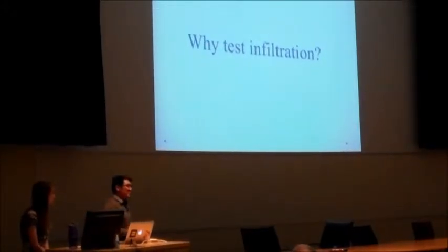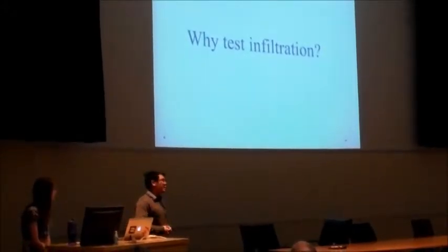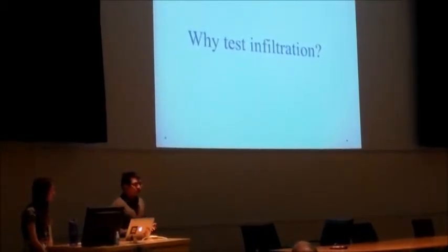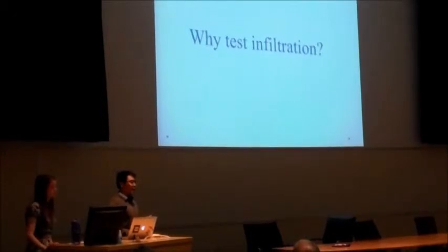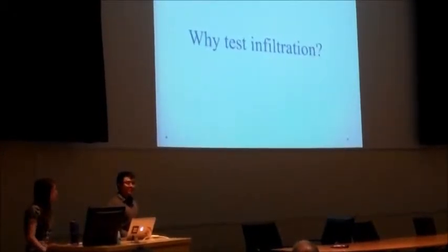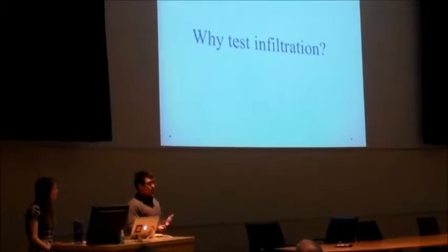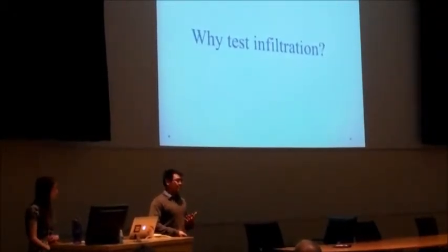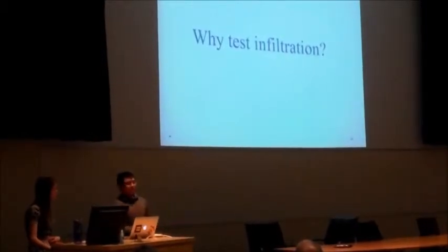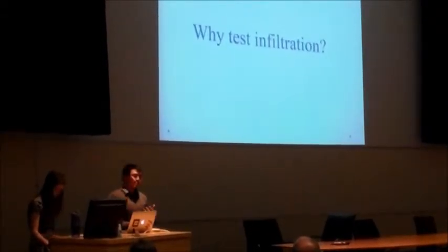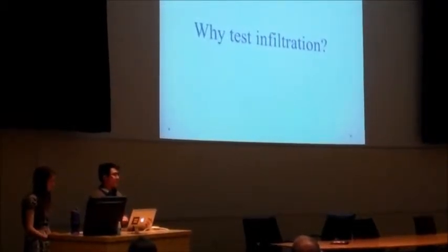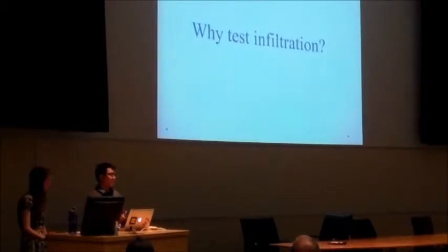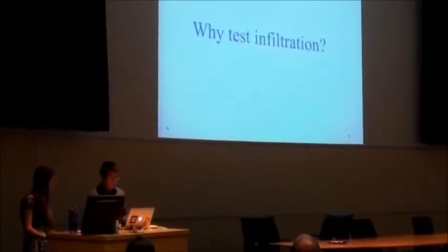So why is it important that we test the drainage or the infiltration rate of pervious pavement? It's because whenever an engineer wants to design a structure for water management purposes, he or she wants to know how much water this piece of infrastructure can manage, and how fast this structure can transport water away from the surface into the soil so that it can be absorbed, minimizing the amount of runoff on the surface.